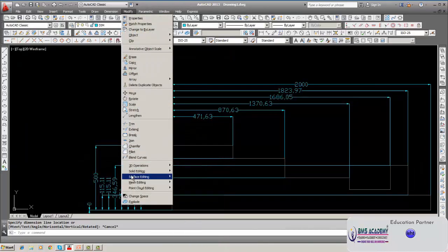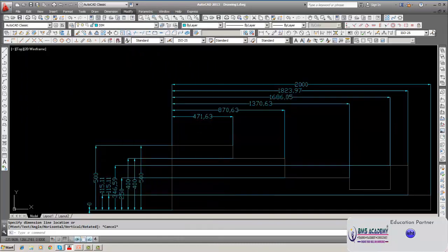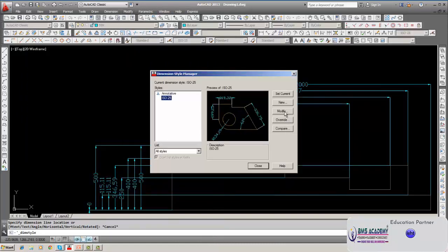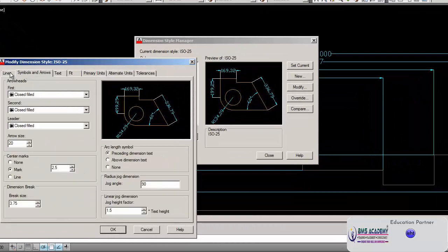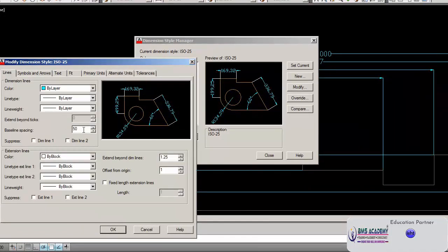Let us see. I have to go to dimension style. Pick up that dimension style, modify, pick up the line. Suppose I change it to 70, let us say.